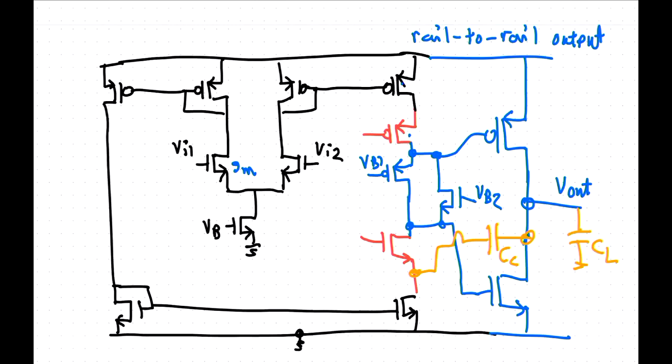Yeah, let's see. I think that's all I want to say for these different amplifiers. So the cascodes, telescopic cascode or current mirror amplifier, the folded cascode, rail to rail input, and the buffer stage at the output. So those are really quite important tools to have. And when you read papers, you're probably going to see references to these circuits a lot.